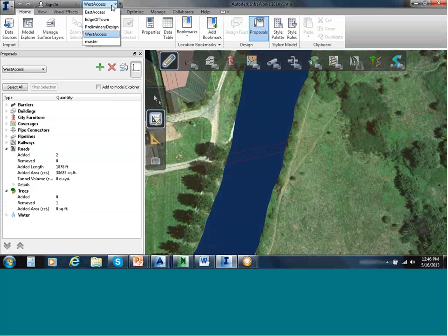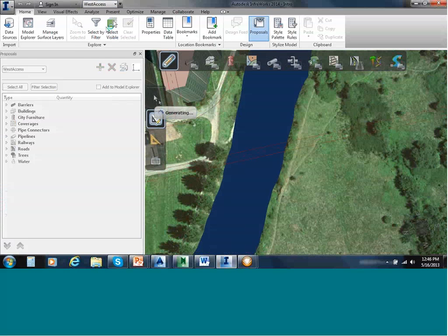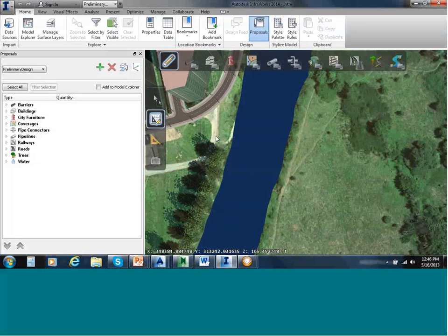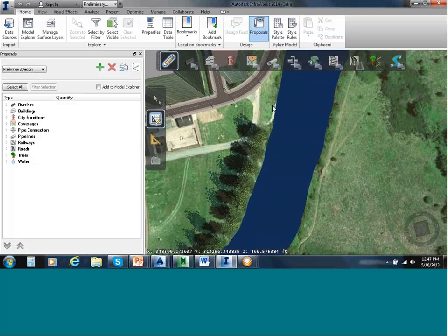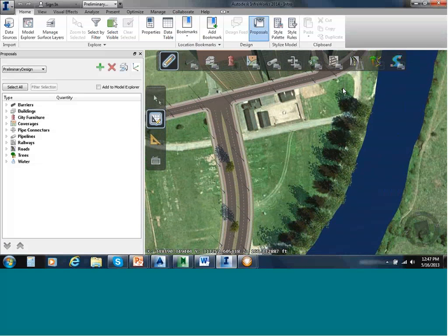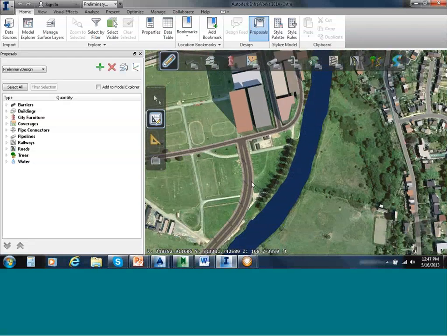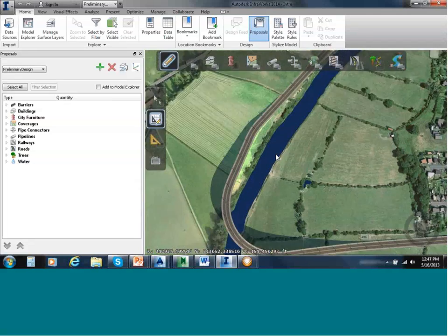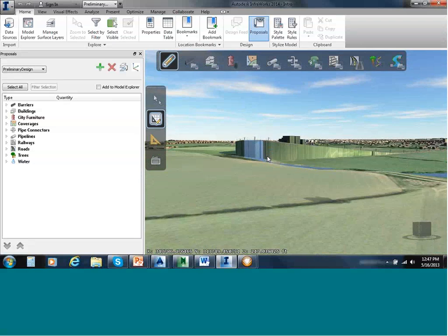Okay. Now the other part is we actually have design roads available to us now as well. And that is slightly different because with the design roads, you have a true 3D model, and you can actually start adding some information to it, some criteria. So we talk about design speeds. We talk about putting in the tangent lengths for those straight segments of the roads, and the curves. You can set your curve radius. You can decide if it's a curve or a spiral-curve-spiral. So there's a lot of different criteria that you can assign to these roads, along with vertical curves.